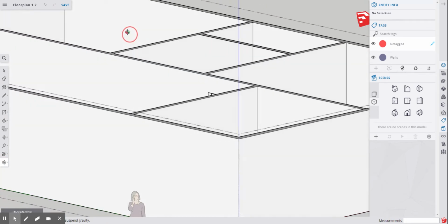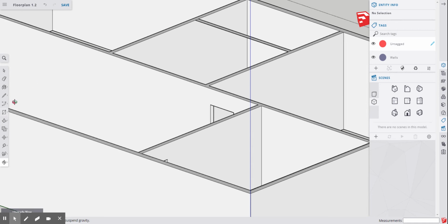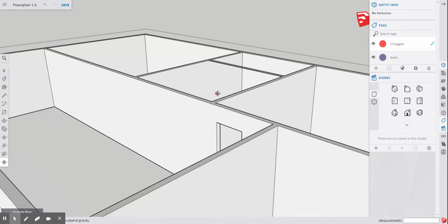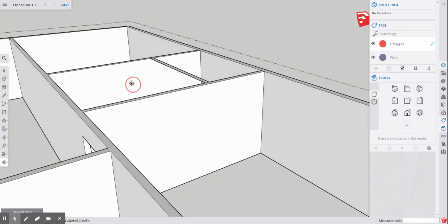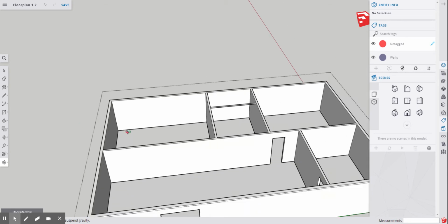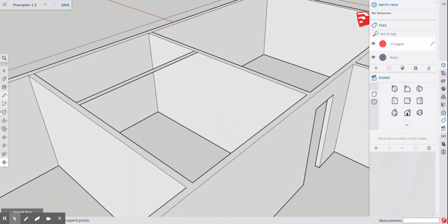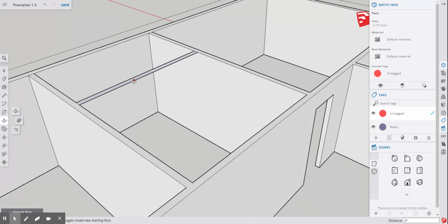Now, this is why we can't forget this stuff. I'm going to go back to the perspective view because I said that was my preference in the other video. Let's see. This is the view I want. Grab that push and pull tool, and I do need to bring it down. Remember, 8 feet or to the bottom like the others.